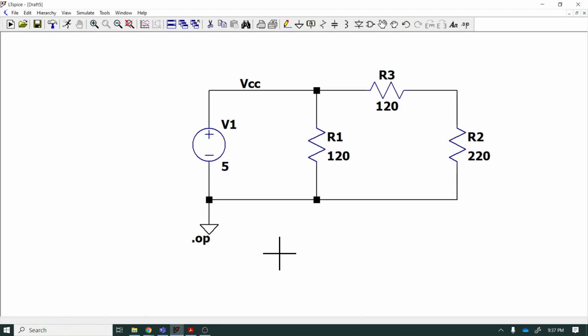Okay. Now, one thing is the simulation is now wrong, although it says like a current through this. That current was for the previous run of the calculation. Again, I'm looking down to the bottom left-hand corner of the screen where it shows the current through the component I'm hovered over. That's going to be wrong because I've now put these resistors here and this calculation was done without those resistors here. So we have to run the simulation again.